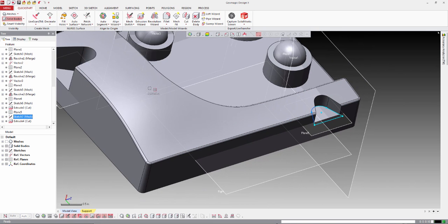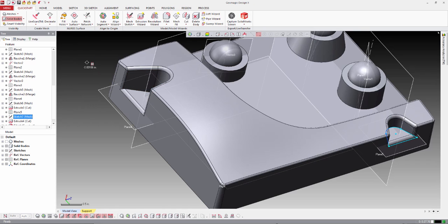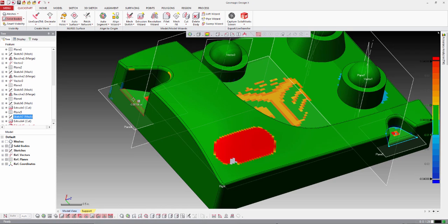At this point, I can run some fillet commands on this edge and this edge, and then we'll hit the estimate button. It'll look at both of those edges. I think they're about the same radius, and it'll apply that radius across both edges. Heck, it might be this edge too. Why not? Let's just do that. And we have that created. Check the deviation of the model. I think that was a pretty good guess. We have those fillets created. Now the last set of features here seem to be in this area, and we'll take care of these last hole cuts at the very end as well.